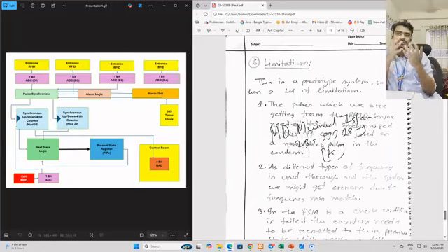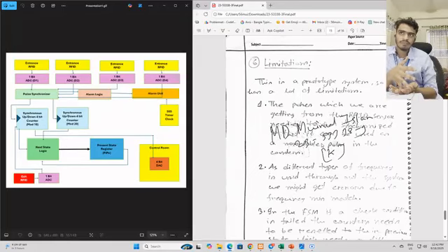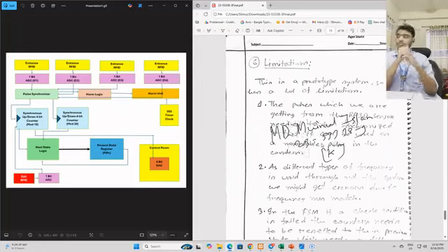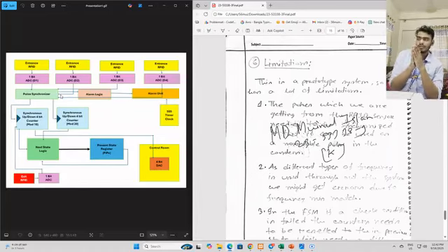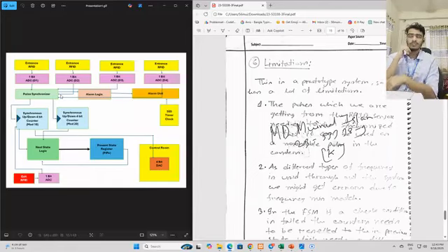The first limitation that I have noticed is the sensor inputs, the ADC inputs. These ADC inputs are coming to the pulse synchronizer. Now this pulse synchronizer is probably not explained in this system because of lack of knowledge, you might say. I don't have enough knowledge, or this TLC syllabus did not cover how we can actually synchronize these signals and send them as a clock, because the counters need a clock, right? If you can't pass the signals directly into the counter, it won't work. So we need to send a clock signal.